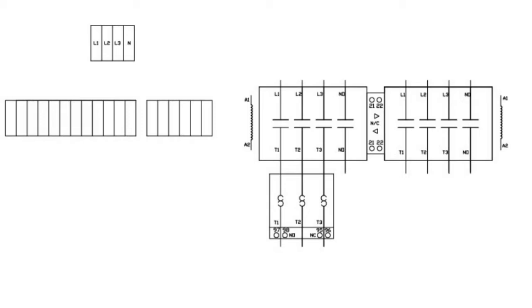Okay, so the control circuit is going to be 120 volts AC. It's going to come from right there. The DC power for the motor, I'll add a couple of blocks in there so that you can show where that power is coming from. Then below that, that row of rectangles, you can fill in the labels in there from the terminal block, whatever terminal blocks we're using to connect things like start buttons and stop buttons and whatever other control devices we might be using.